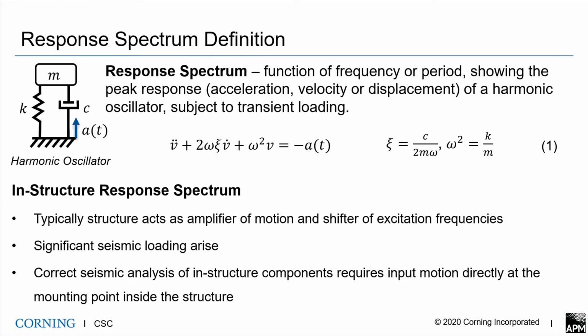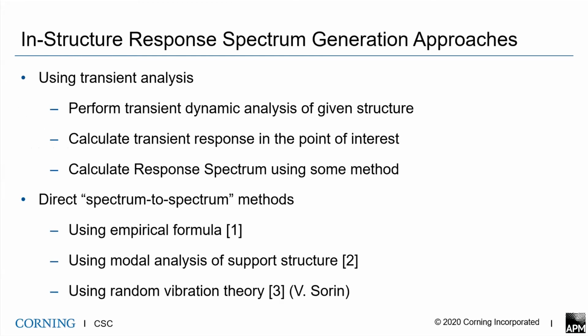So correct seismic analysis of in-structure components requires input motion directly at the mounting point in the structure. But more often, initial seismic information is known only for the structure's base. Consequently, the problem of in-structure response spectrum calculation arises. So how do we calculate the in-structure response spectrum?